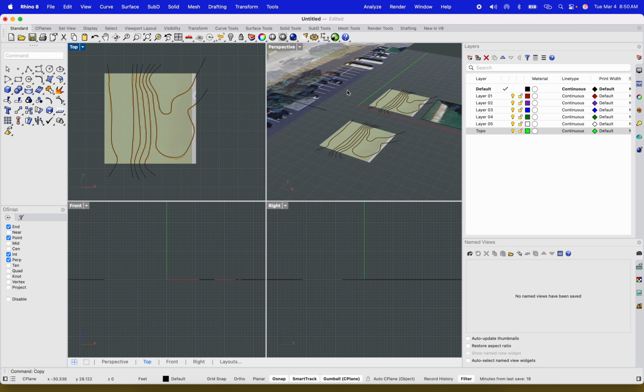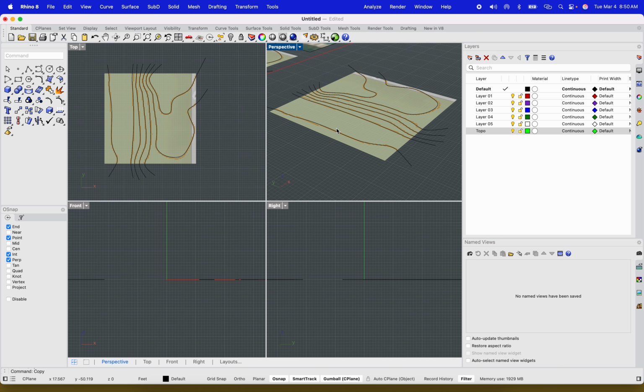Let's take a look in 3 dimensions and make sure that it's flat. If it wasn't flat and I accidentally clicked on something, have I shown you guys what you can do? How do you make things flat in Rhino? Anybody? Any guesses? Flatten. No, I'm just kidding. Make 2D, right? If it's 3D, make it 2D, right?